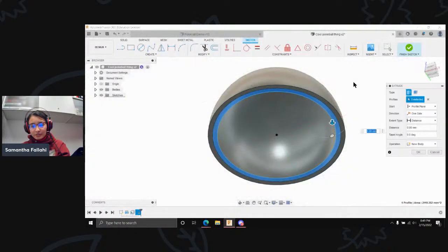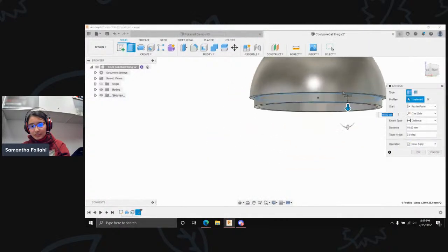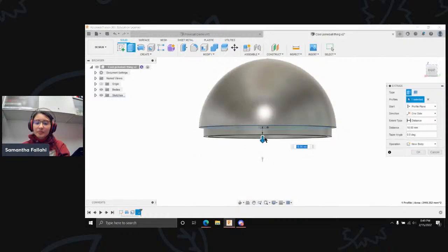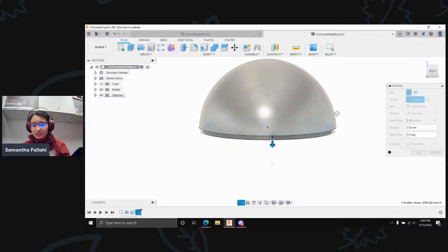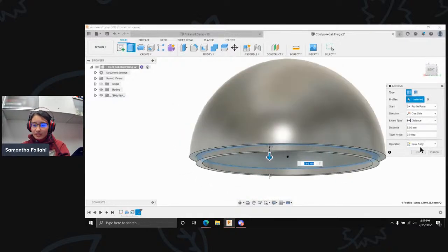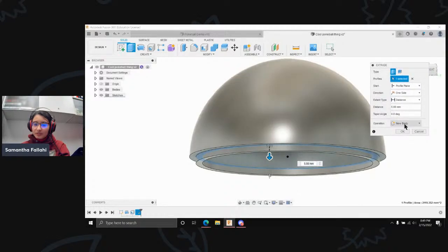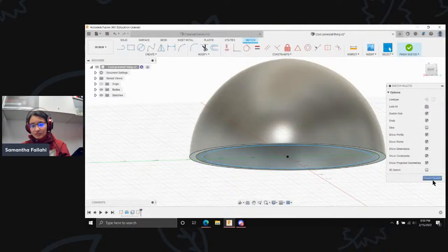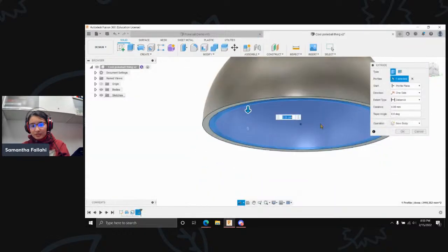What we want to do now is extrude that out. And you can see we have a little band spanning the area. So again, bring it as high or as low as you'd like. World's your oyster. And over here, you see the little operations tab in the extrude window. We have new body, join, cut, intersect, new component. What we want to do is have a new body. And what that does is it makes a body separate to, whoopsies. Go back there. There we go.